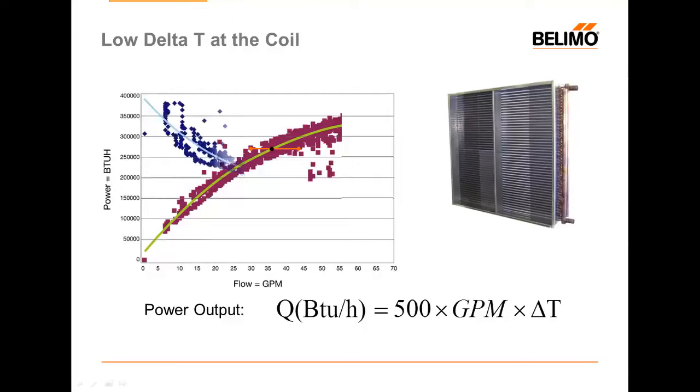So let's add delta T to this graph. And you can see here that as I put more flow into the water for the same load, I will see a reduction in the delta T value. So if my load is fixed, flow and delta T become inversely proportional. So at a fixed load, less water means higher delta T. This curve has been truncated at a point where it is no longer efficient to pump additional water.